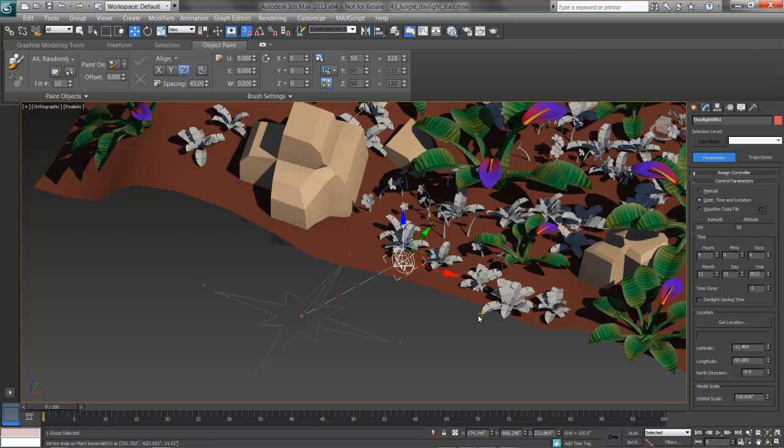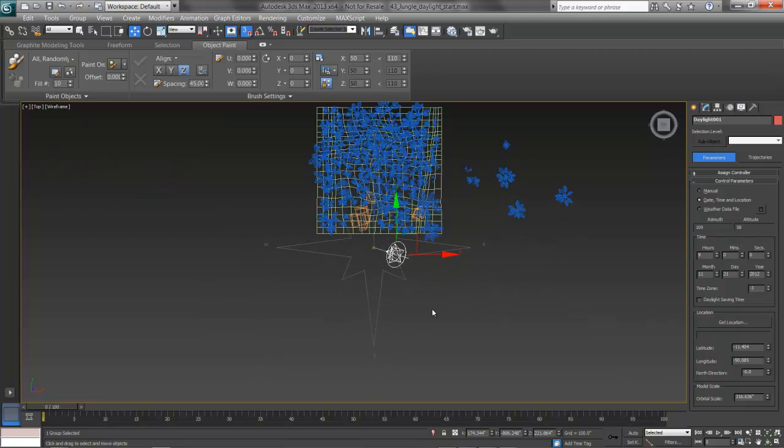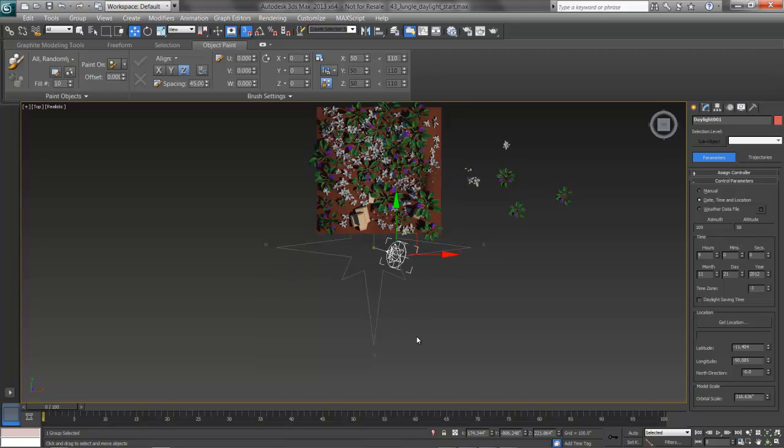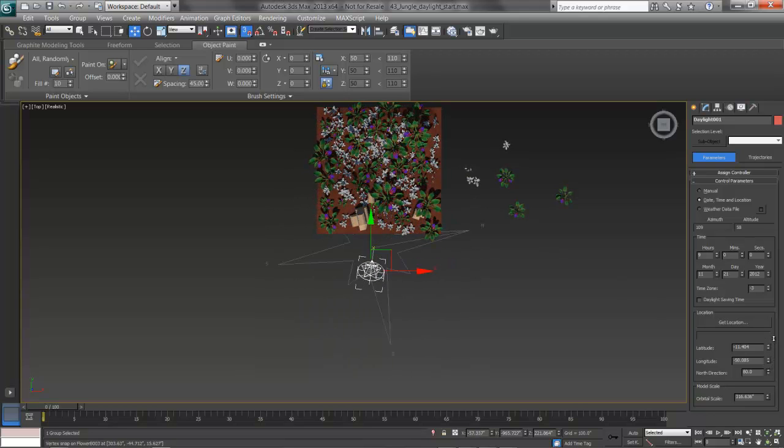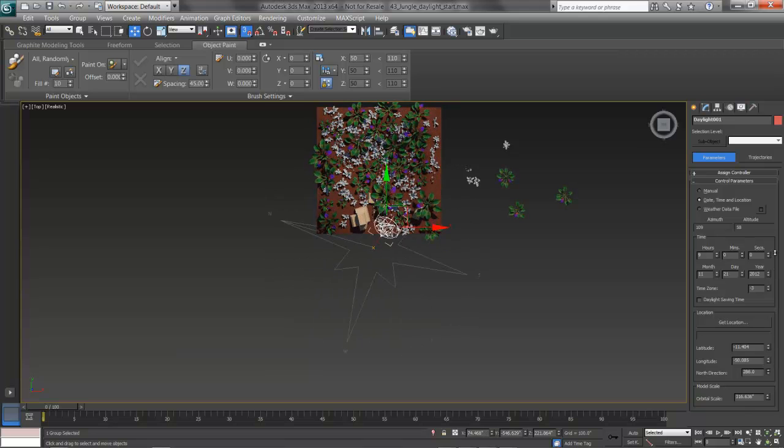Finally, if we need to swing around the north direction, we can. At the moment, in a top view, north is straight up. Here, as we can see in a wireframe, or just looking at where west and east and south are, north is straight up in the scene. Using the north direction in the daylight, we can swing that compass around if we need, and we can see those shadows changing. I'll pull mine around slightly, and put east just a little off to the side, let's say.